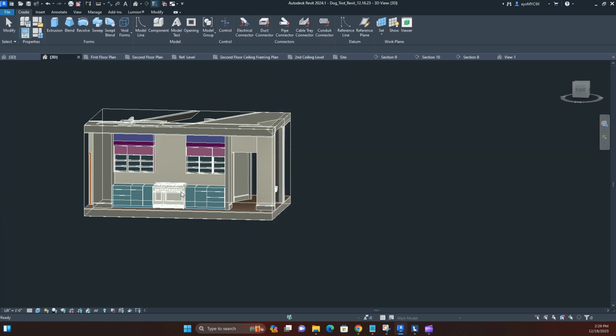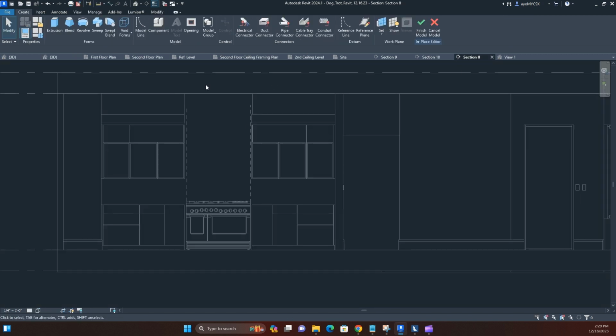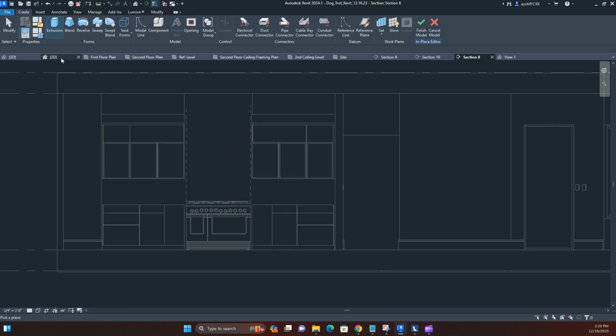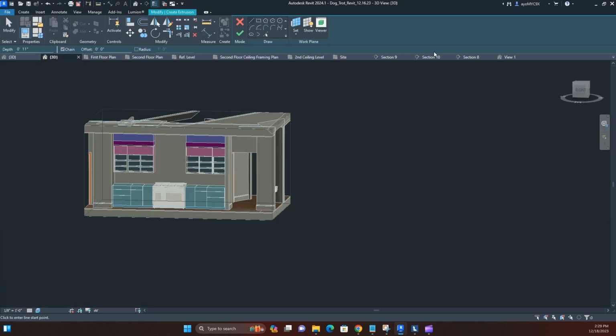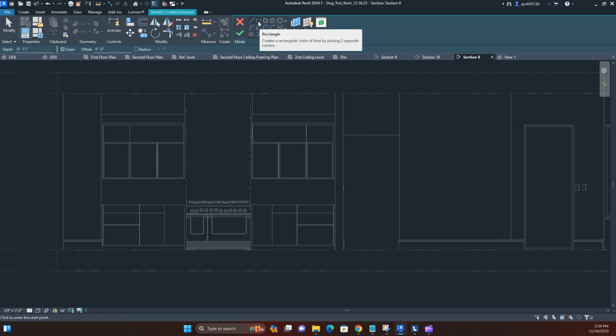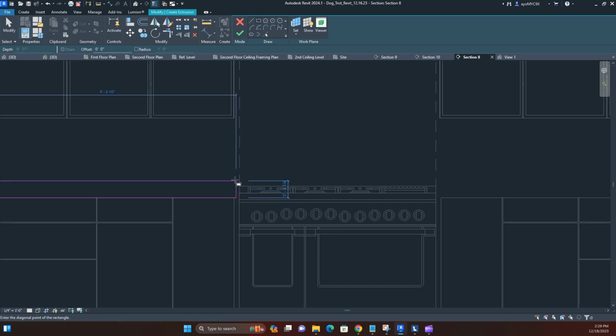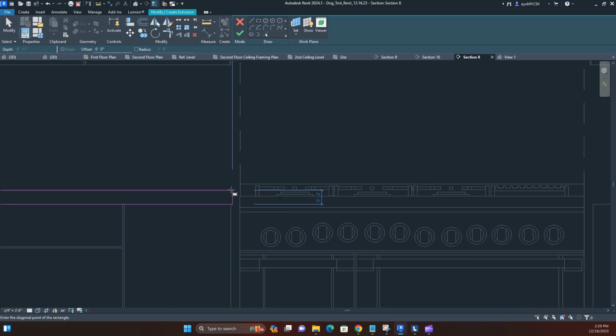Generic model. Go back to the same wall. Extrusion is the same plane. I'm just going to pick the plane again just to confirm we are working with the same plane. Draw a rectangle, go from one side, stop right beside, before your range. You want to stop right before it.